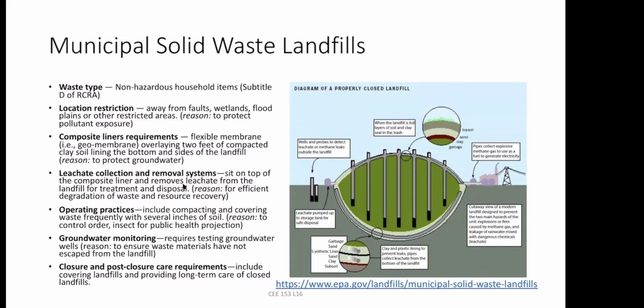You have to have a leachate collection system because most of this municipal waste is actually food waste. It will decompose and produce this slime, or water, and that water has to be captured because you don't want to let it fill the entire landfill. Those compounds are toxic to microorganisms, which means they will not degrade anymore. So that's why you have to collect and treat the leachate.